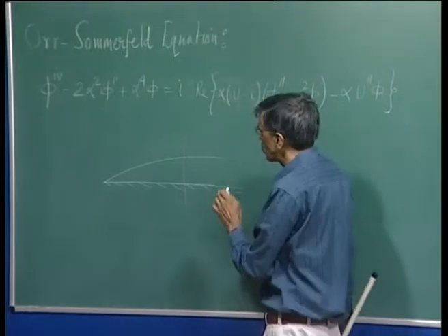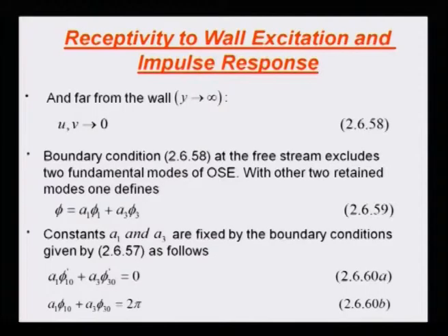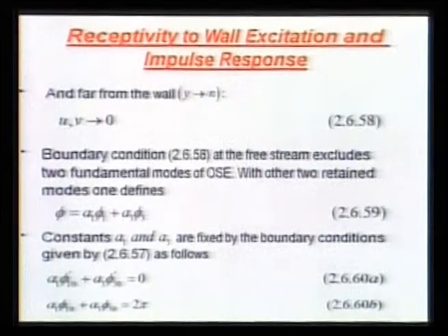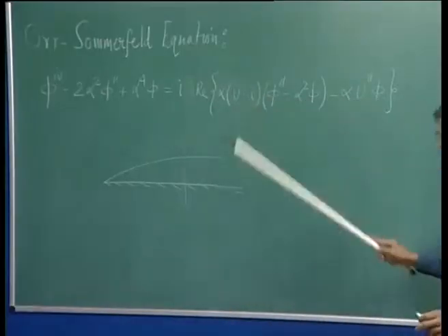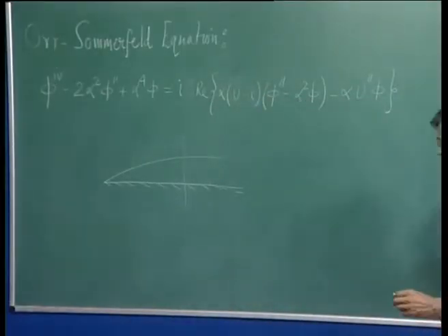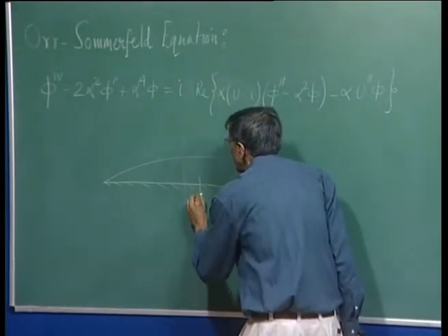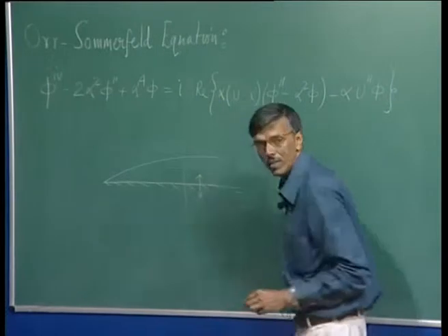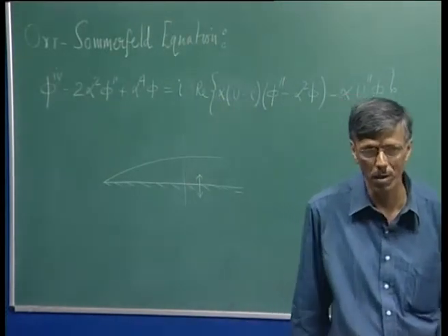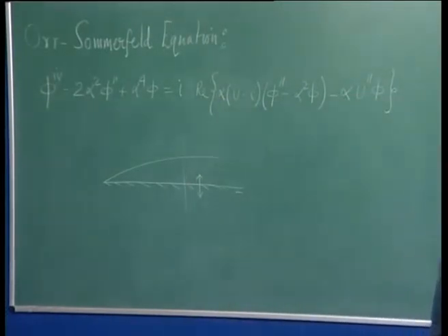So, if I want to study the property of the shear layer to wall excitation under the Orr-Sommerfeld umbrella, then I would provide a localized disturbance like the one that we noted was performed by Schubauer and Skramstad. Now, this is a delta function.